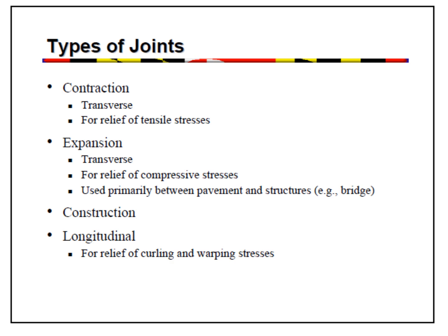It regulates the location of the cracking caused by dimensional changes in the slab. Unregulated cracks can grow and result in an unacceptably rough surface, as well as water infiltration into the base, subbase, and subgrade, which can enable other types of pavement distress.